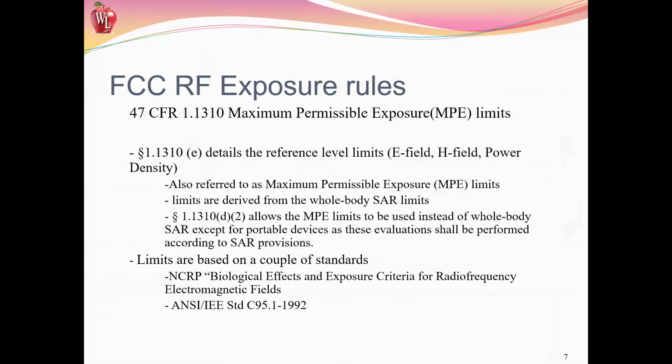RF exposure, maximum permissible exposure. They reference the levels, the level limits. They look at E field, H field, and power density. It's MPE. The limits are derived from the whole body SAR limits and allow the MPE limits to be used instead of whole body SAR, except for portable devices, as these evaluations have been performed according to SAR provisions.